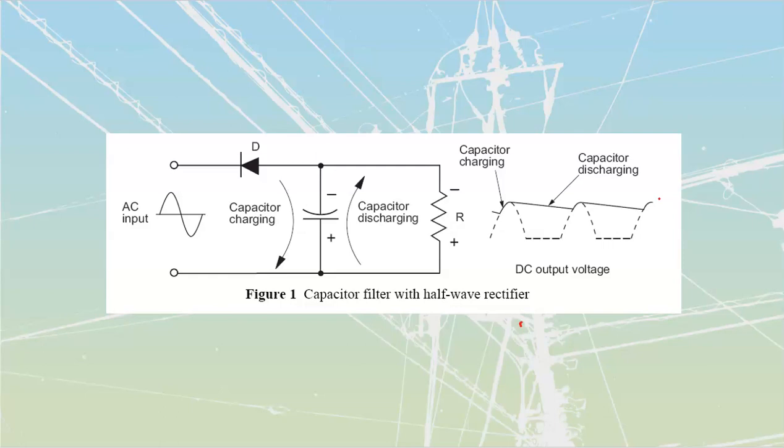to these capacitors. They'll also otherwise sometimes have a white stripe down the side of the capacitor, or they're going to have a set of positive, negative, plus, minus marks. Those are going to be on them as well. You do need to make sure that you follow polarity. An electrolytic capacitor cannot be connected in reverse, because what happens then is we're going to reverse the oxidization. So we're going to strip away the oxidization, then have to rebuild it in the opposite direction.